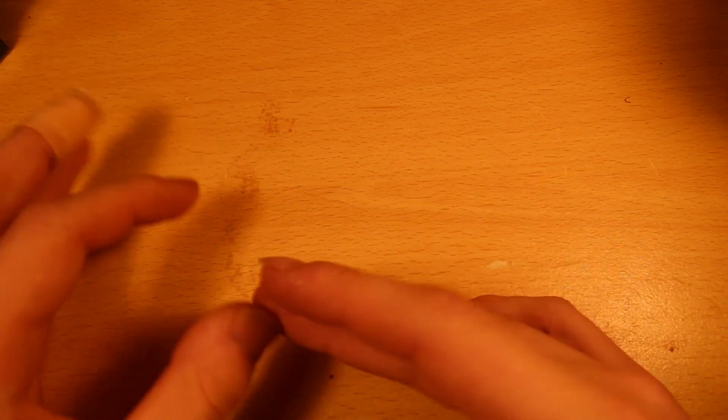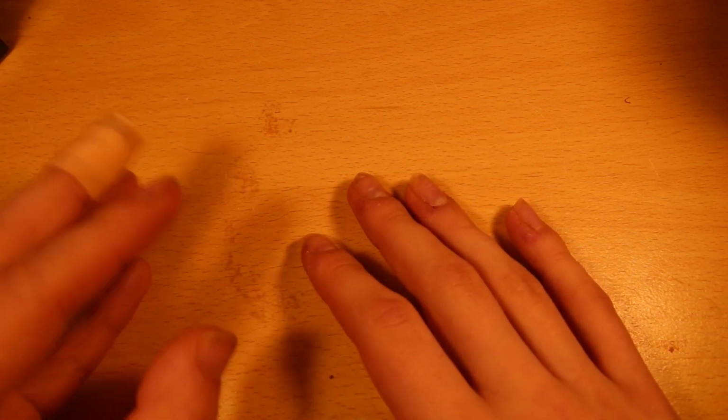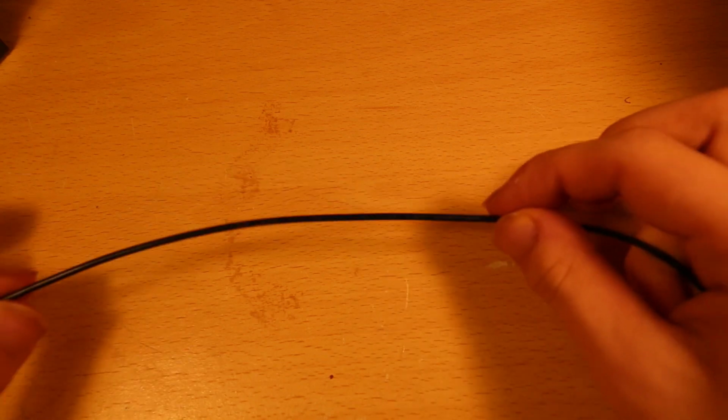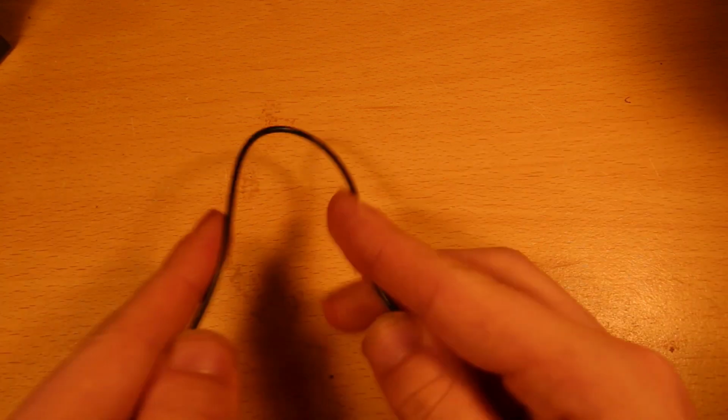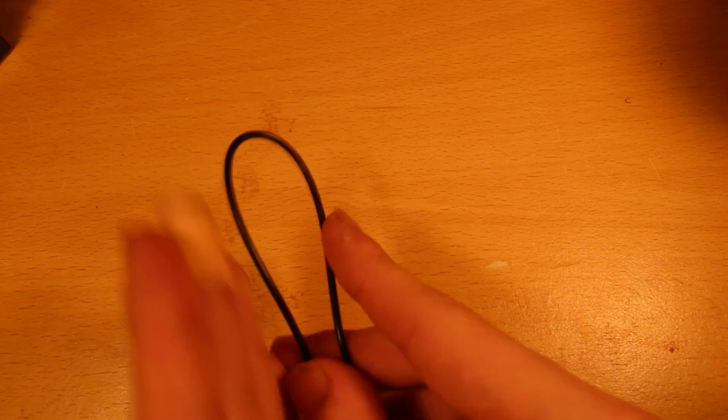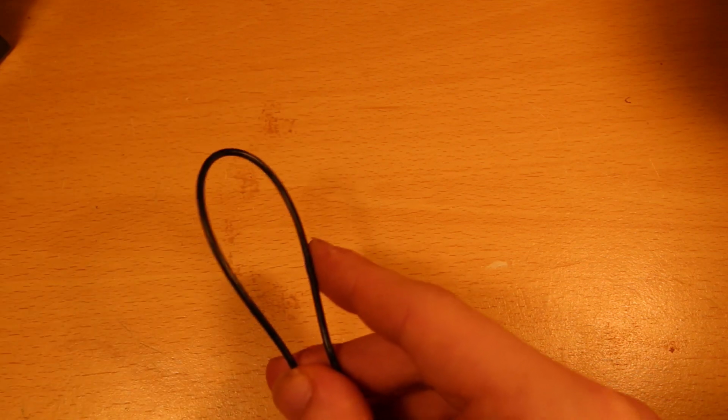The other thing that I wanted to mention was that I talked about all the weird effects you get, like capacitive coupling and inductive coupling and that kind of thing. All of that gets way more pronounced at high frequency. So when you start getting into what's called RF, which is radio frequency territory, things get so messy and ridiculous. It gets to the point where you can have a wire like this, and if you're passing an RF signal through the wire, and I bend the wire like that, the signal will then stop coming through the wire, because it will come up here and then reflect off the angle and come back down again, rather than going round.